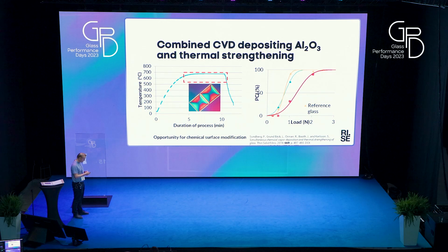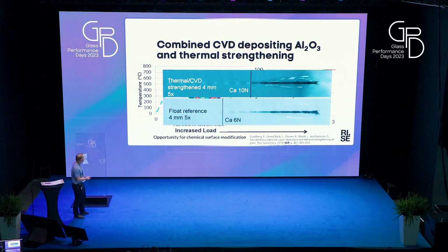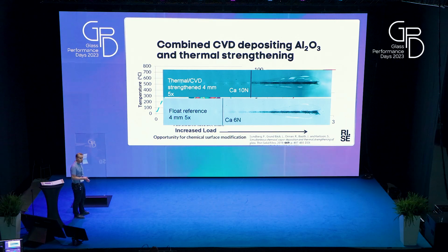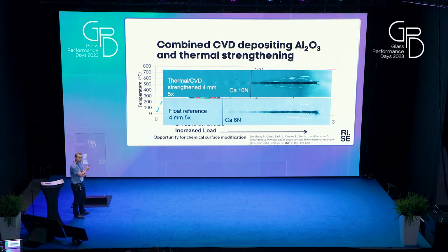And here is an example of the crack resistance, which I will explain a little bit more about later on. But you can increase the crack resistance, and that's basically keeping K1C low. And here is also some example on the scratch resistance, and that you can increase the scratch resistance by this. And it's fairly simple. We did this in the lab, and I think it's not too difficult to build it in a tempering line either.